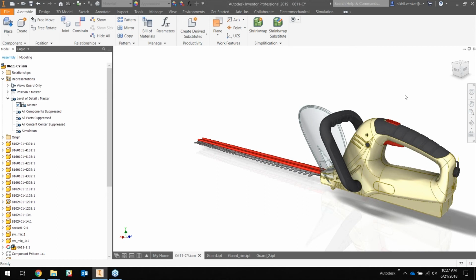Okay, and we have something here to clarify from something you said earlier, Nikhil. Josh is asking, did you say you would want to do a nonlinear analysis anytime a curved surface meets a point, or is it anytime a curved surface meets a straight line? Well, it's anytime you have curved surfaces meeting a point, meeting a straight line, anything that may lend itself to significant stress concentration by contact. I don't mean little holes and notches, but significant stress concentration by contact. Maybe you want to look at a nonlinear analysis.